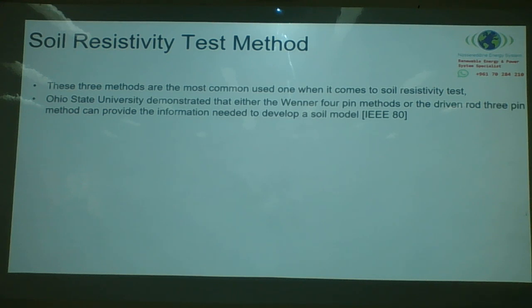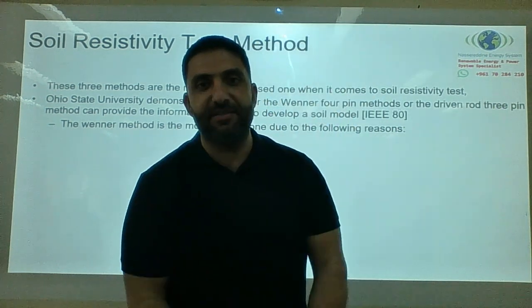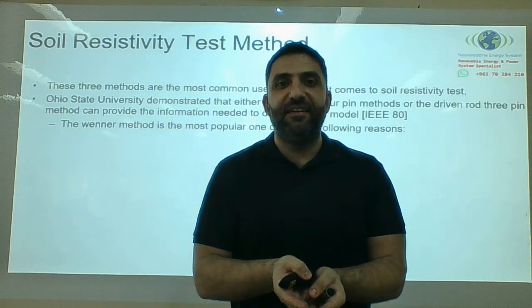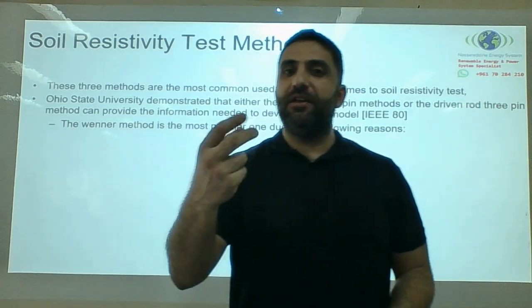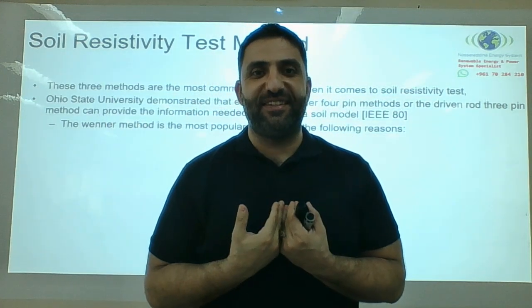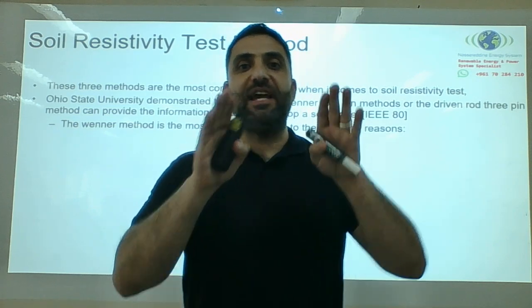These 3 methods. Now, Ohio State University demonstrated that either the Wenner 4-pin or the driven rod method can provide the information needed to develop a soil model. Like I said, in a separate lecture, we'll talk about the soil model. So now it's been proven, and it's evidence that I can use either Wenner or a driven rod. These 2 will give me sufficient information to establish an adequate